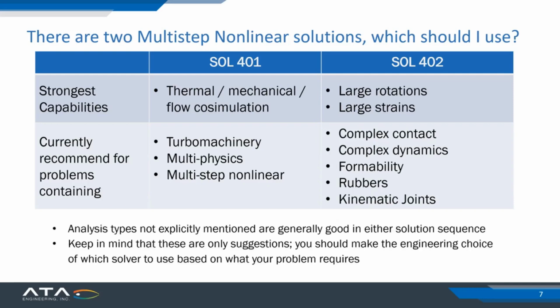So obviously, I didn't mention all of the analysis types there, and that's because generally speaking, for most nonlinear analysis that you might do, either solution 401 or solution 402 is an acceptable option. So if you're just doing plasticity or doing plasticity with large displacements, for example, those are absolutely capable in both of those solvers. Either 401 or 402 can do that.